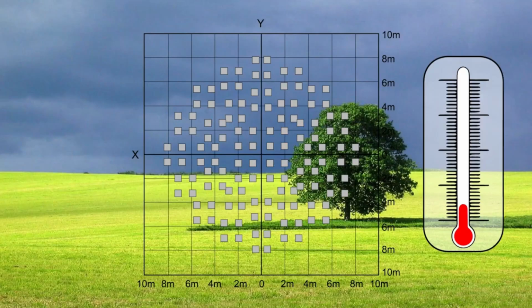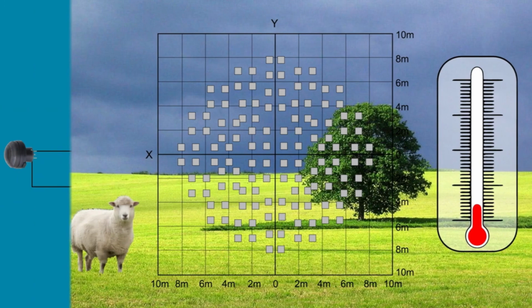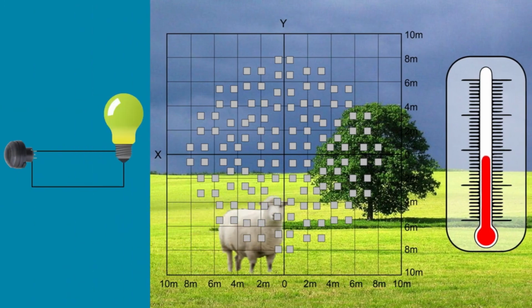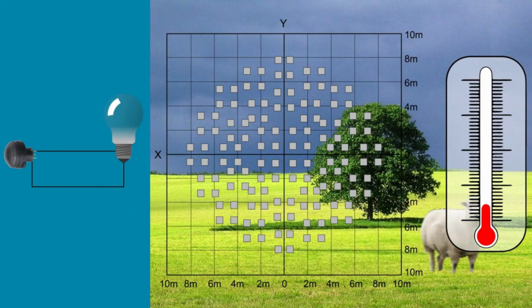So when an object, say a shape, passes in front of the background, the temperature at that point in the sensor's field of view will rise from the ambient temperature to body temperature and then back again. The sensor converts the change in infrared radiation into a change in the output voltage, and this triggers the detection.